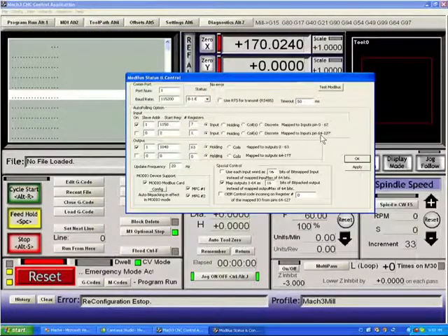Brian Barker, for example, has hooked up a potentiometer to control his feed rate override. He simply sends it in from the ModBus into port pin 64, and he uses a macro pump to continuously monitor that value, and as it changes, he changes the feed rate override. Therefore, it's almost invisible to you as a user. You turn the pot and the feed rate override goes up and down accordingly. We'll have to explain macro pumps later. Obviously, at this point, if you've never heard of one, you're wondering what a macro pump is. It's simply a block of logic that runs repeatedly to tell the program to do something.